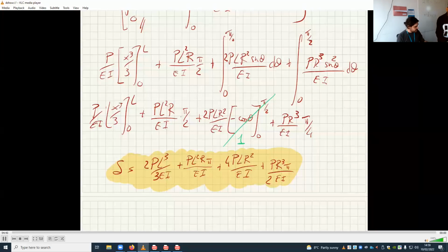So is this the right way to do it? Sigma 1 minus sigma 3 is the diameter of the Mohr circle, so that is 2 tau max. Yes, that is good. So then if I just substitute tau max, the factor of safety is twice sigma yield divided by tau max. I don't know if this is what you've done. Then from this, if I find my pressure, P over 2 is tau max. No, it's sigma 1 minus sigma 3. So this is wrong.